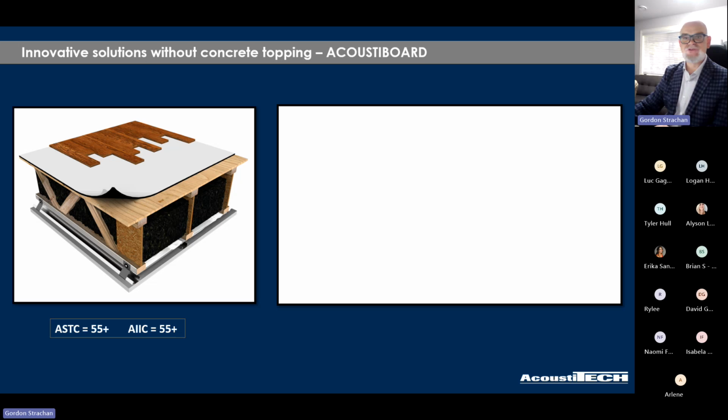So this solution is when we're using recycled rubber and felt to come up with a solution. This is a board from Suprema. Now, this product is specifically made for use with engineered wood and laminate floated applications. You can do other products over it, like an LVP or a ceramic, but then you're putting layers of plywood over top, which isn't always the most economic thing to do in today's world. So this product, I tend to say, is perfect for your engineered wood floated applications because of how easy it goes down in these spots. And you're going to watch them do it right now very quickly.